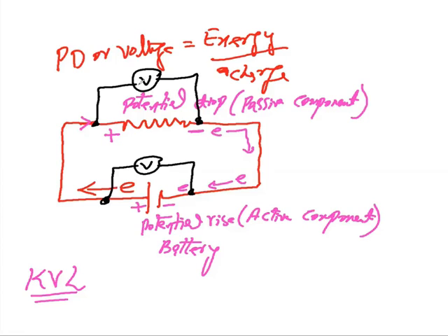So that's why the voltmeter gives me the potential difference, the voltage, and we must keep the resistance of this voltmeter infinite so that no current passes across it. All current will pass across this. If some current passes this way, there will be a heating effect, and that will destroy my voltmeter. It will also affect the results, because the voltage calculated would be greater than expected.